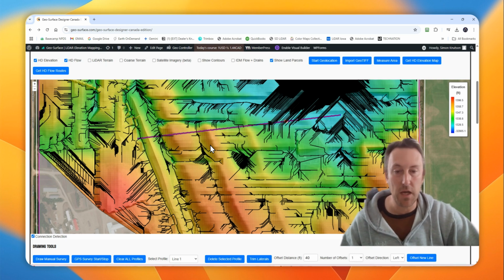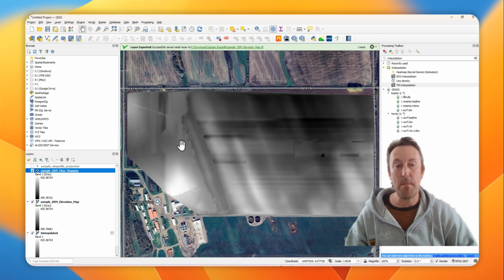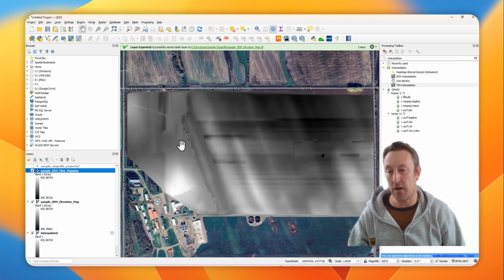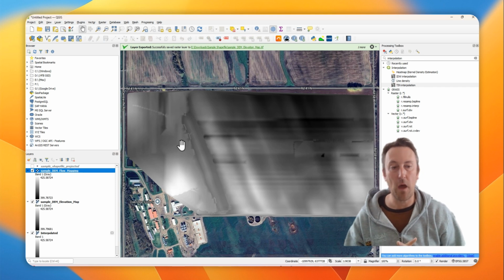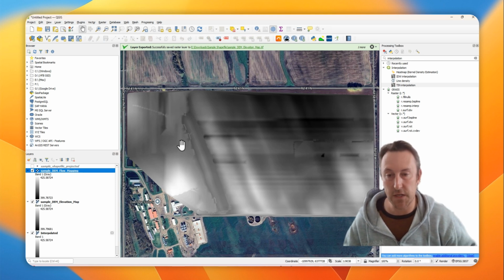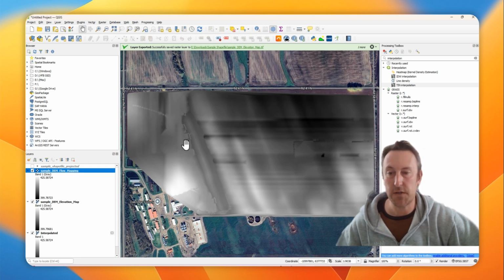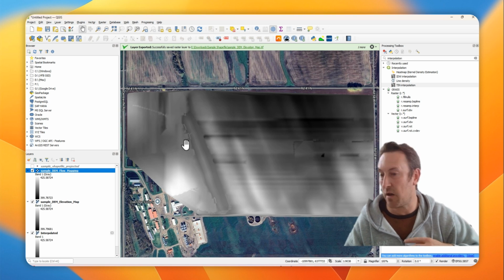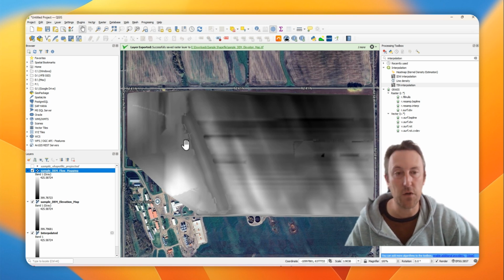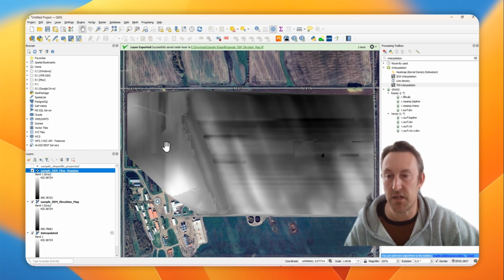Final thing I'll show you here is, just in case, let's go back to QGIS. Imagine your shapefile data or your original data were in elevation units of feet, and you need to change those to meters to give you accurate values, because we expect the incoming data that we're using in Geo-Surface to always be in meters, and we actually convert it behind the scenes back into feet.